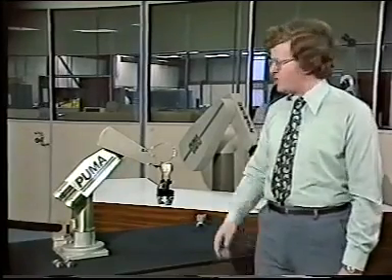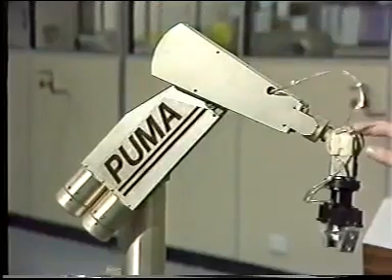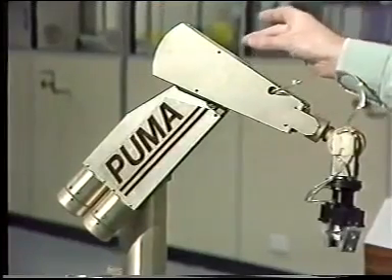The PUMA is designed to solve precisely the sort of manipulation problem we're interested in, that of moving objects from one place to another and one orientation to another in three-dimensional space. And to understand how PUMA solves that problem, we're going to have to look in some detail at kinematic structure. Now, you remember from the text that this is going to involve identifying two fundamental types of component, links and joints. The links are the rigid parts of a system, like these, and the joints are where links come together.